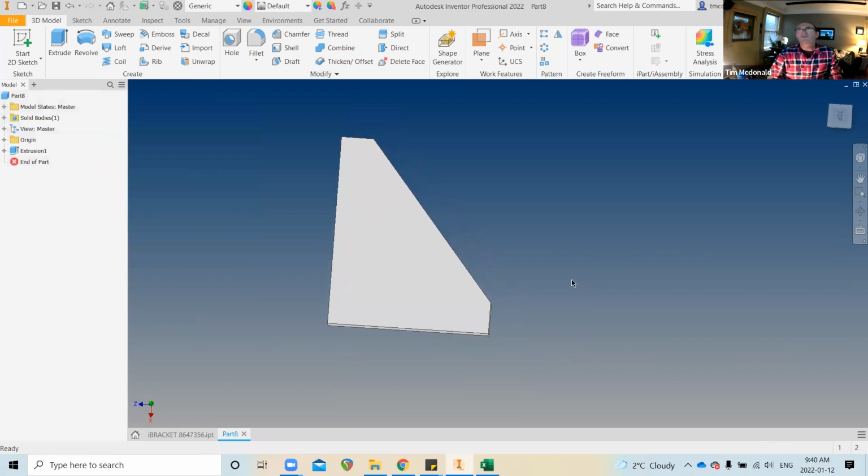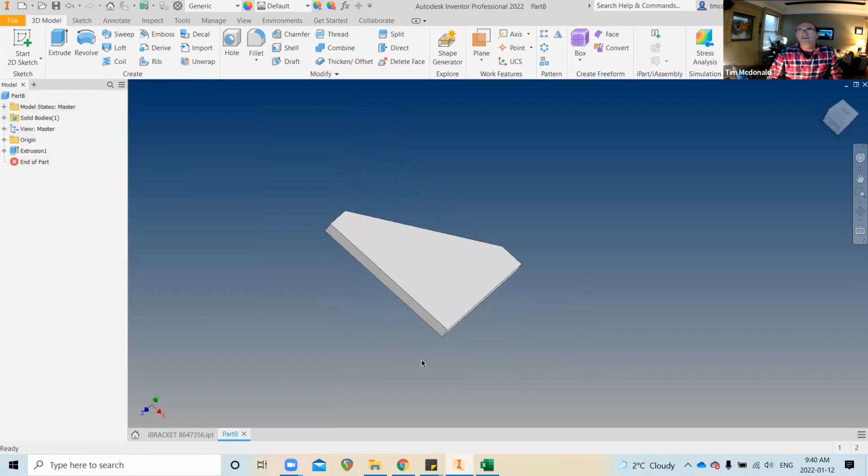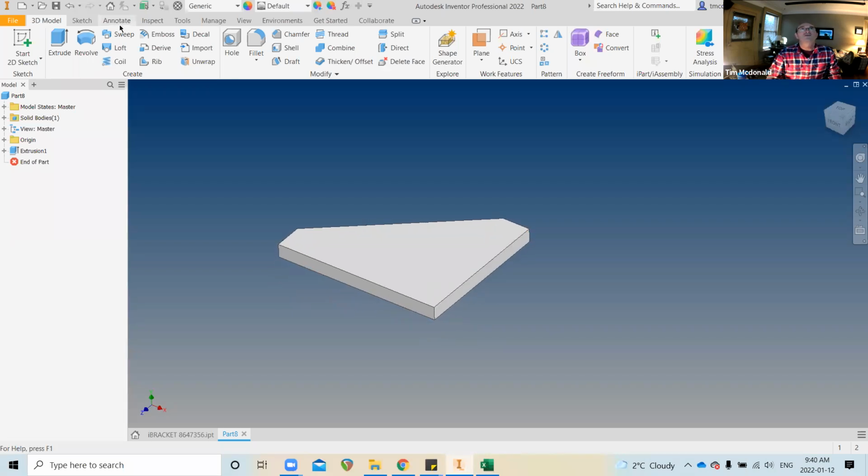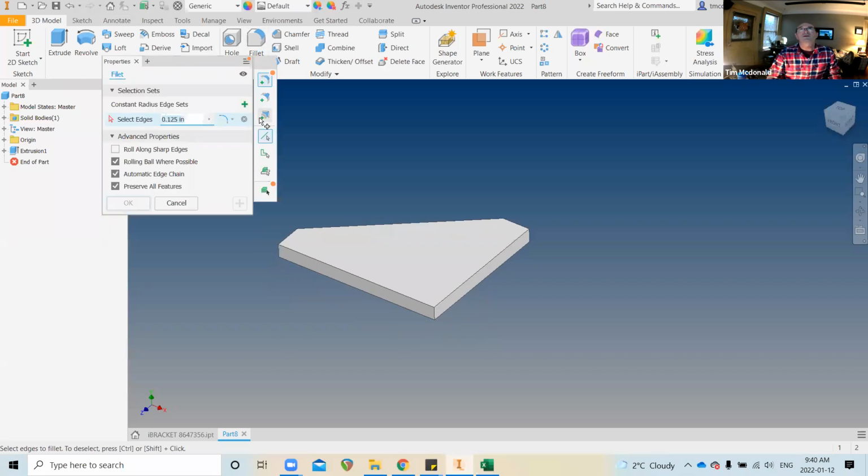Okay, so the only problem I'm having with this gusset is the fact that it has no radius on it. So I'm going to come in here and put a fillet on here. I'm going to make this 0.5 so it matches our 1/4 inch gusset. And I'm going to change the name of that before I do this. I can leave the 0.5, but we'll call this fillet. Sure, why not? Fillet equals 0.5.